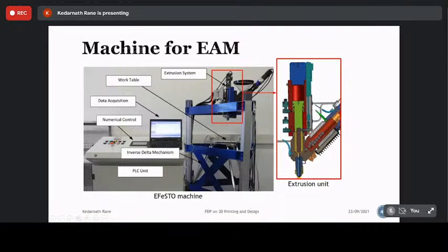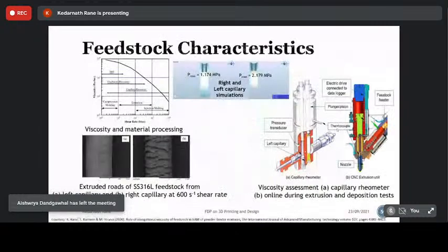I'm not going to cover the system, but these spherical, metallic balls ensure the polymer feedstock is molten and homogenized evenly before the melting and extrusion itself. Although we mix it as a feedstock, this system ensures that the material is very highly homogenized before extrusion. So that is one of the merits of this system, and you can get very homogeneous deposition through this kind of approach. So let me consider some of the research aspects that we consider.